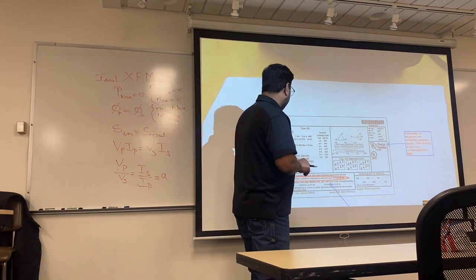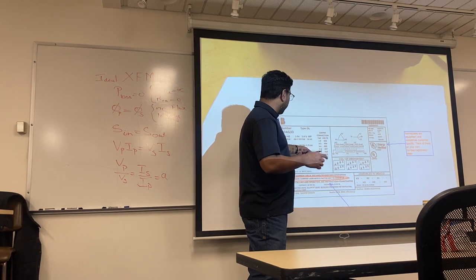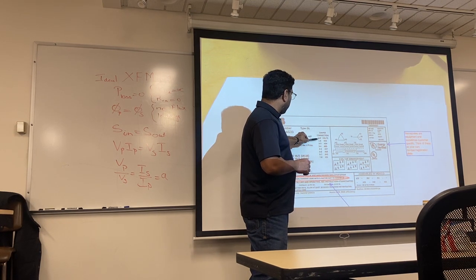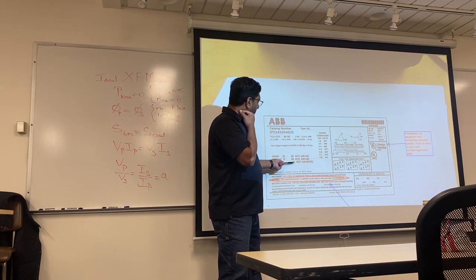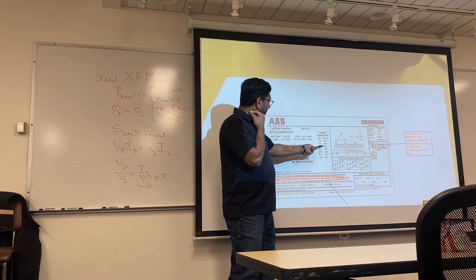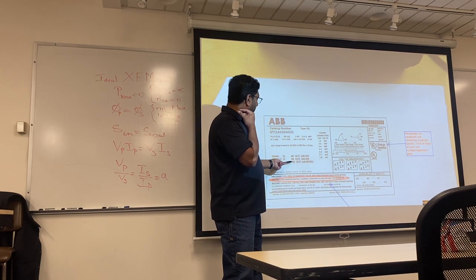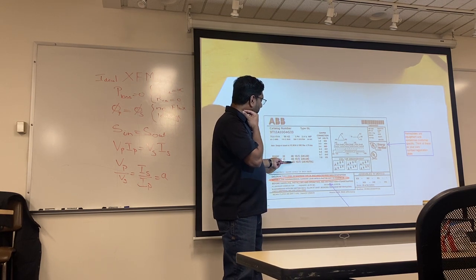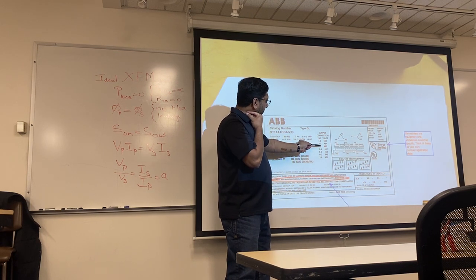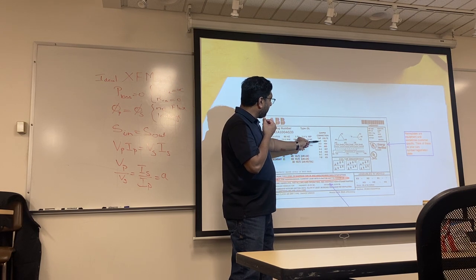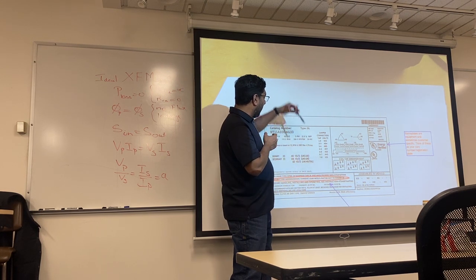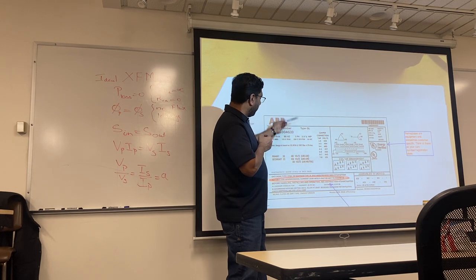And this is meant for the last class, but since it's here, imagine this. You wanted a 120, and you were thinking at 480 that's going to do the job, and for some reason you are not getting 120, you are ending up with 150. What we as a power utility would do is, we will still guarantee you the 120. Rather than going between jumper connections 3 and 4, we will go to either 1 and 2 or 2 and 3, so a higher voltage, thereby picking up your voltage to 120.